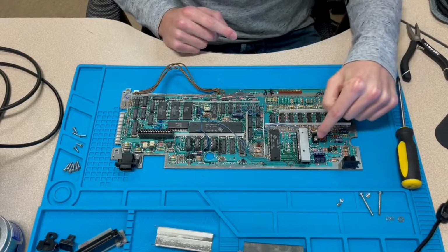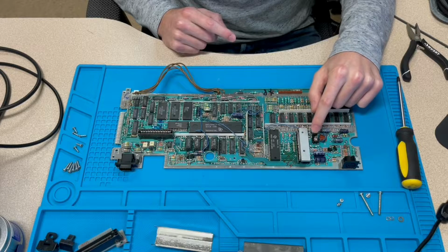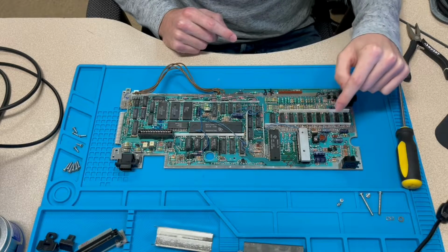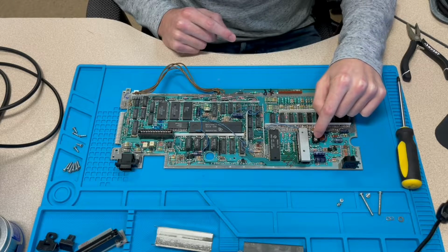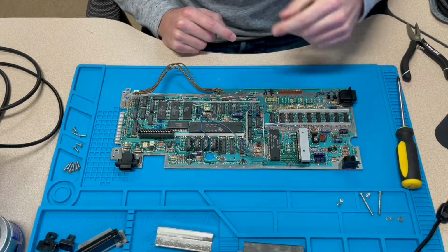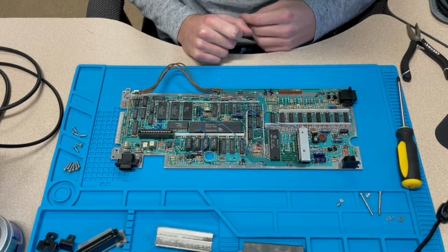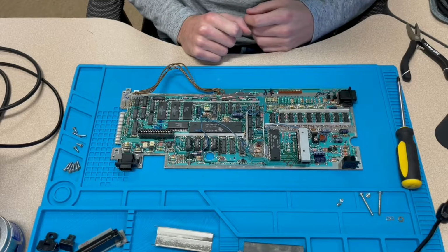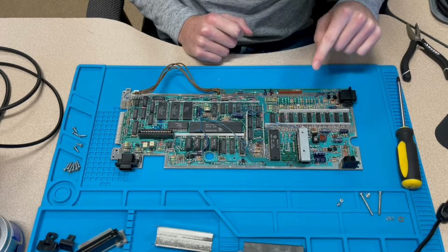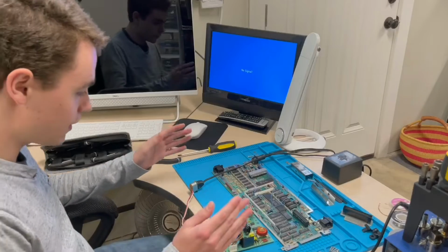There is a potentiometer right there, and it's next to a crystal oscillator that I believe is for the video circuitry. So there is hope that if I turn this potentiometer, it might restore the color back to the image, because maybe it's not supplying enough voltage or it's just in the wrong position somehow. So I'm gonna get a little flathead screwdriver and turn that and see if that makes any difference whatsoever to the image.